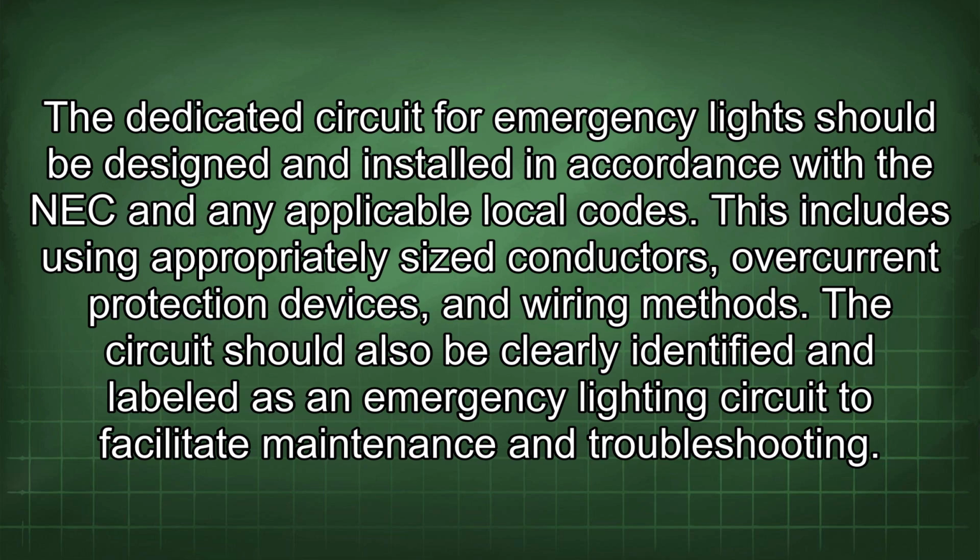The dedicated circuit for emergency lights should be designed and installed in accordance with the NEC and any applicable local codes. This includes using appropriately sized conductors, overcurrent protection devices, and wiring methods. The circuit should also be clearly identified and labeled as an emergency lighting circuit to facilitate maintenance and troubleshooting.